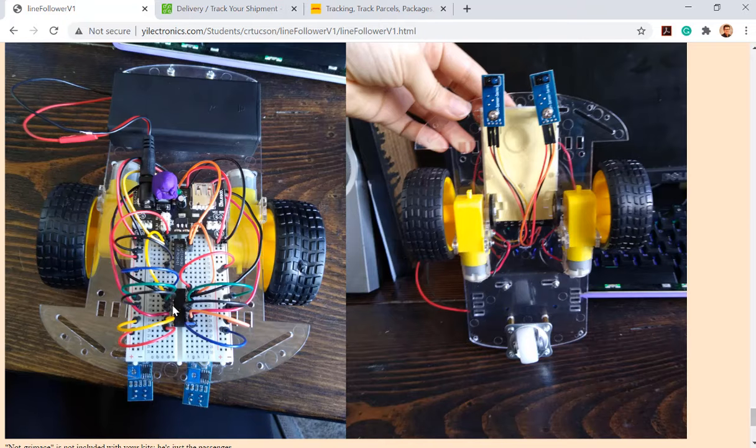So here's the design procedure for a circuit. This is a really simple circuit, but I'm trying to let you know this is an intro level course, right, for circuit design. So I just want to let you know what's the standard procedure to design a circuit for application. So you design the circuit schematic, and you assemble everything on a breadboard, and you test it. Okay, after you know it's going to work, you convert everything into a PCB, a printed circuit board. So you have PCBs everywhere. So the motherboard in your desktop, in your smartphone, everywhere there are PCBs. The copper traces are being printed on the board.